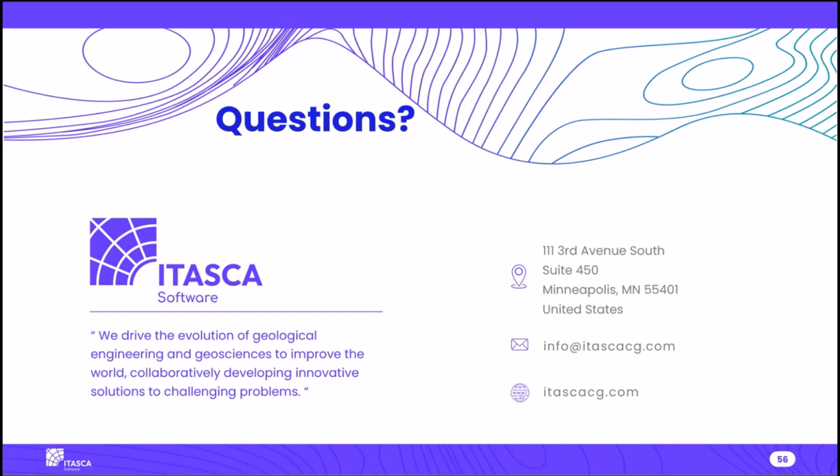Great. Next question. Have you also compared with local damping? Yes, I also compared the local damping for that one-dimensional site response, but I did not present it here. My results show that local damping is not suitable for dynamic analysis and is quite different from the other dampings. So local damping is not a selection for dynamic analysis in FLAC3D. Yeah, I've had a similar experience with local damping.